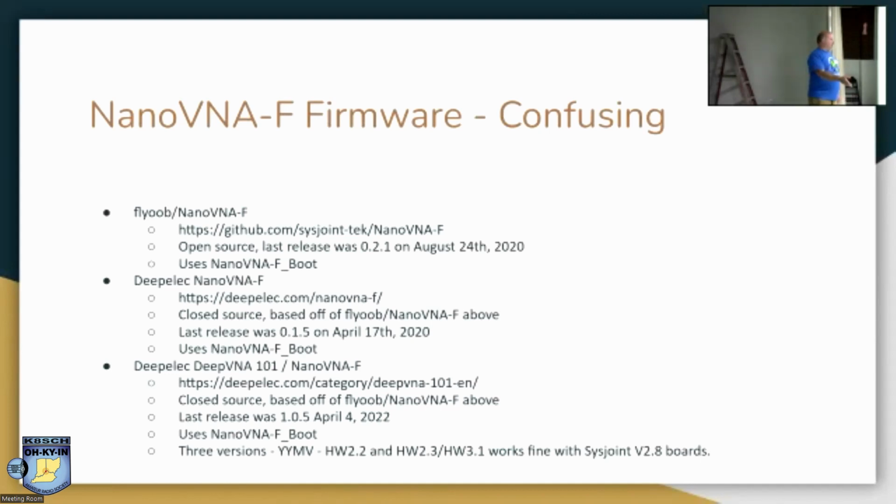And then you just drop the bin file in there, and it will unpack itself and install it for you. The older version, you had to actually hit a switch to go into reset mode. It was messier. I ended up flashing the ROM with the bootloader that gives you the disk, so I can't go back with it. Just be aware of that. I haven't regretted it. I like this new version better. Like I said, it works fine with my hardware.